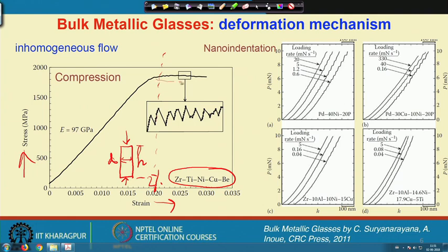However, even though there is little plastic deformation of less than 1%, if you magnify the stress strain plot, you will see some small serration type of behavior, and this serration must be linked with localized strain bursts, meaning somewhere a sudden strain appears, which requires some activation, and then again there is some flow and a drop, that is an undershoot, again some overshoot, again undershoot, and so on.